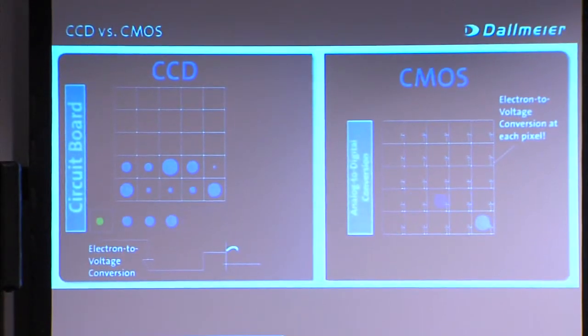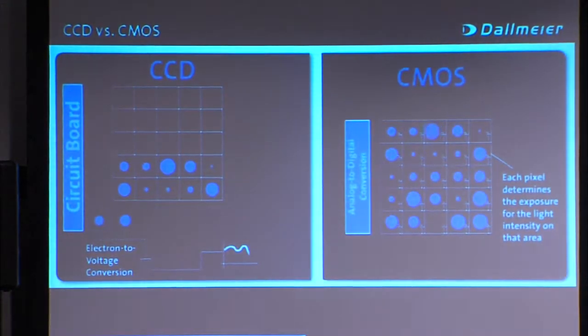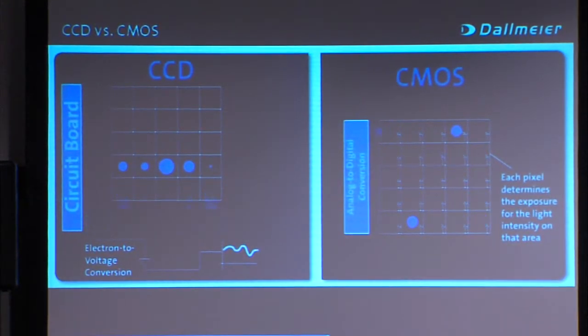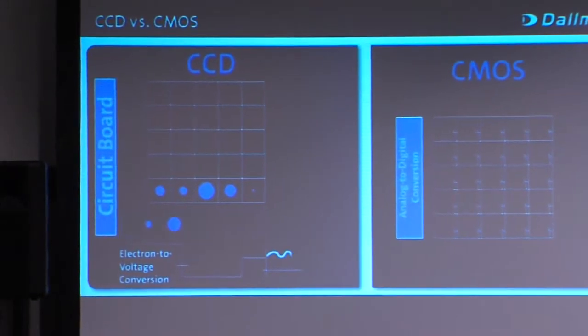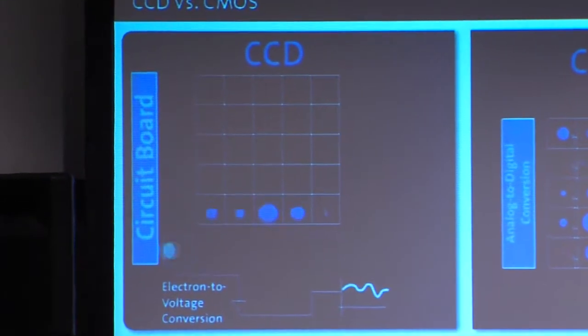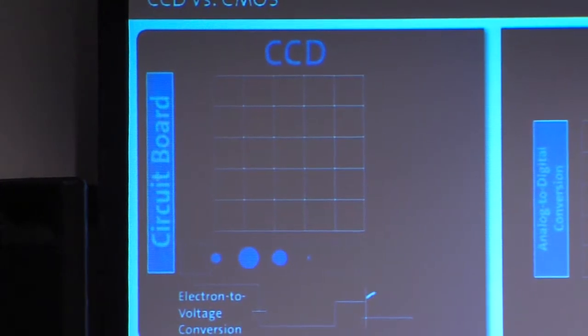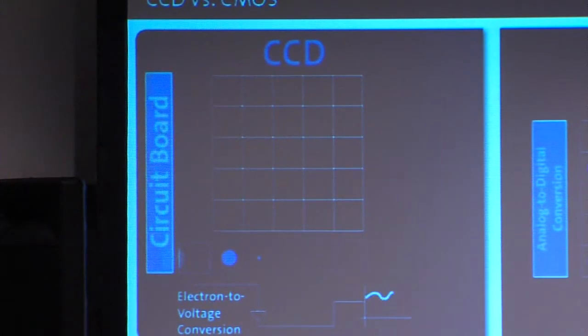So what I have up here is a video. Instead of trying to go back and forth with the video, I just want to explain what this is talking about. In the presentation, I'm going to cover it more. What this is showing is the difference between a CCD camera and a CMOS camera, and how you actually access the camera. Keep this image in your head. What's happening on the CCD side is we're transferring the charges in parallel, and then in parallel down, and then we're serially shifting them out through a converter.